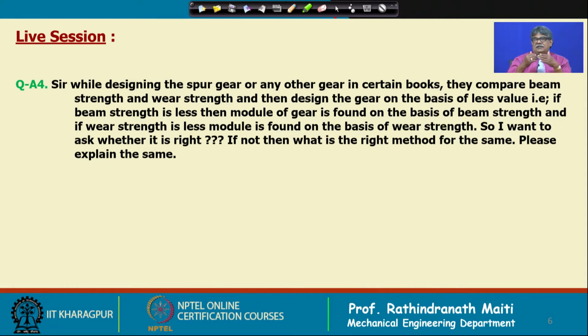On the other hand, the fatigue at the contact will occur, because it is touching and leaving, touching and leaving. So, you will find ultimately when the gears are rejected, there are small pittings over the surface. Okay. Now, in industrial design, what we do, we take a material, or we may consider the material later on. First, from the bending strength point of view, we find out the module, then we verify the state of the material, whether that is capable of taking the wear load also.